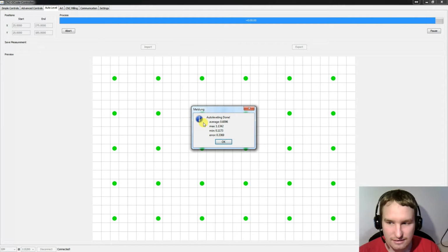And when the end stop is hit, the motor will be stopped immediately. And this can lead to losing some steps. So what I'm doing is, if some steps are lost, so the two measurements from the same point will have different values, I will then use the difference and calculate it over all measured points so that the average is nearly the same. I don't know if it's useful for someone. In my case, it was every time, like here, some part of a millimeter.